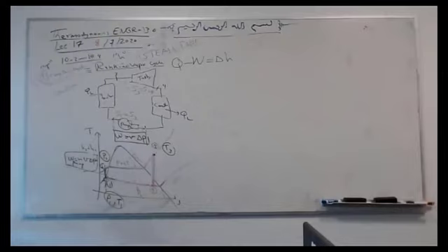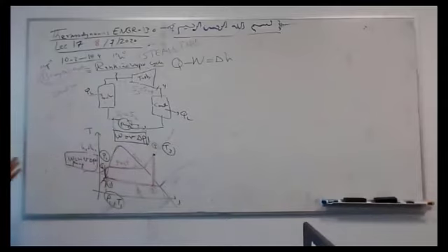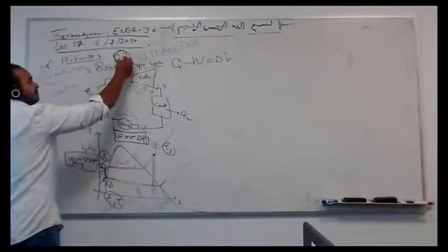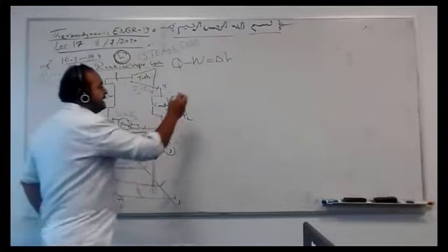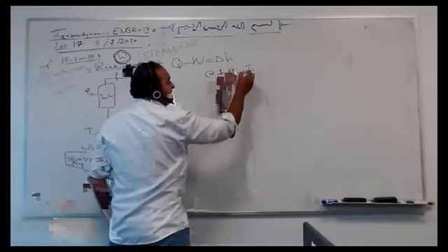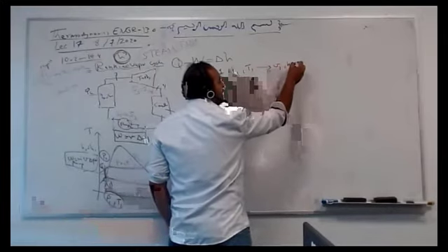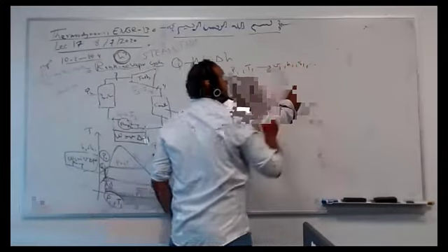So the work in the pump is VdP. Let's say you have P1, T1, P2, T3. I can get everything. It means I can get all the enthalpies. How? Let's take step 1. At 1, you have P1 and T1. You can go to the chart. You can get V1, you can get H1, you can get S1, you can get anything. Correct?